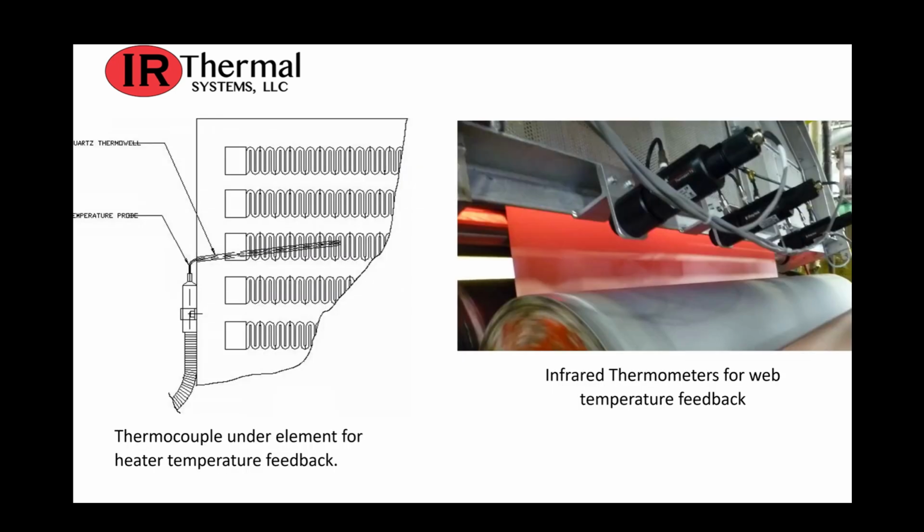So here's a couple of examples. On the left, you have the thermocouple under the heater element for heater temperature feedback. And on the right, you could see those infrared thermometers, those black thermometers that are installed for web temperature feedback. That's where you're actually looking at the temperature of the product.